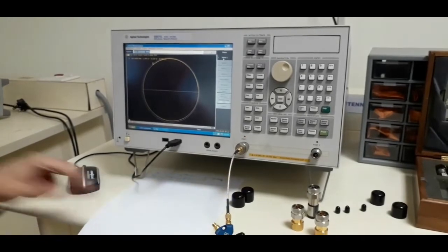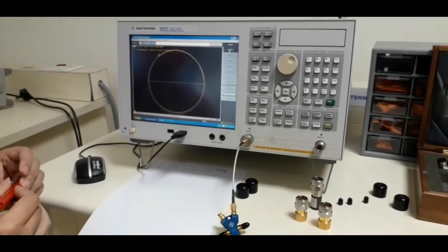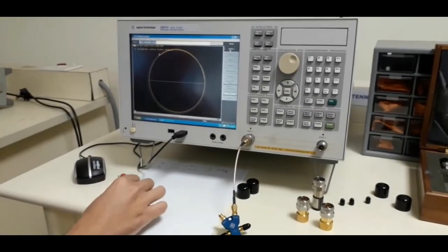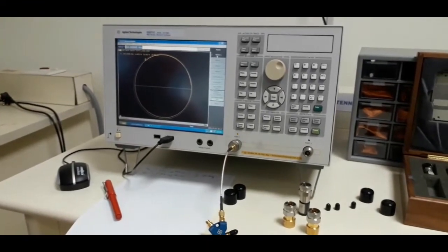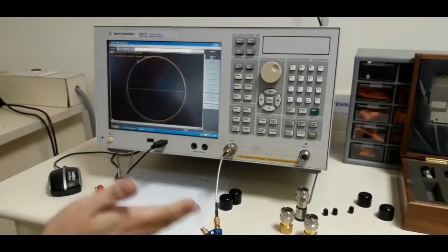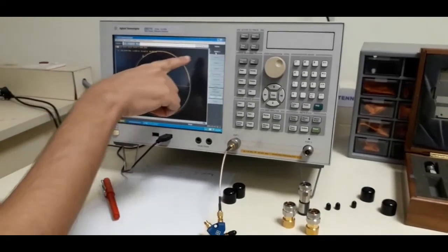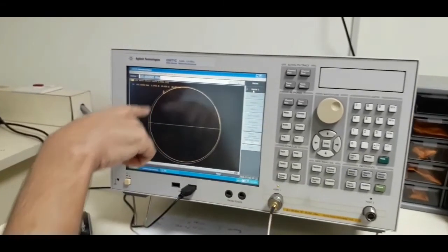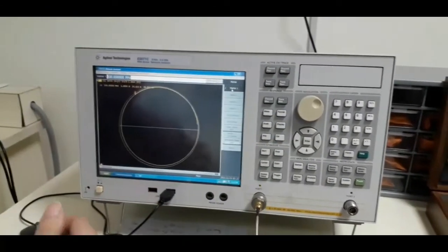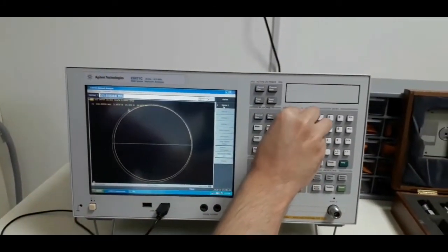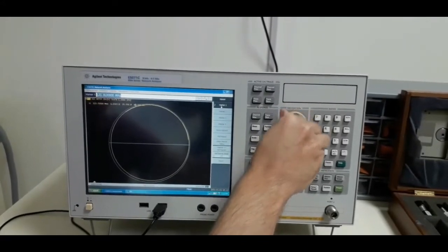Now for the beta measurement, you will need to look at those points where the open or the short circuit impedance sort of repeats. So what you can see is that at 100 megahertz we are at this point. Let us see one more frequency where this same impedance point is repeating. So now I am moving.